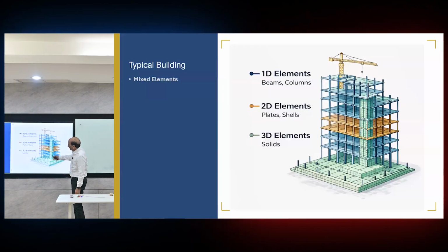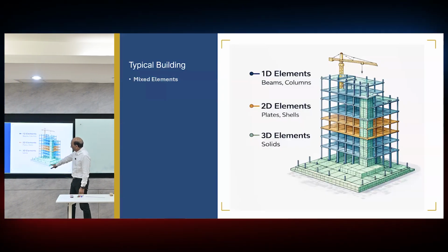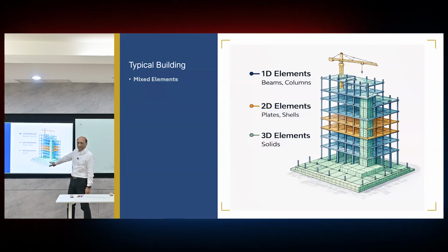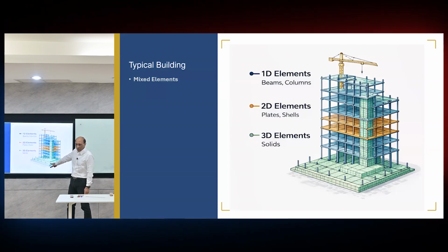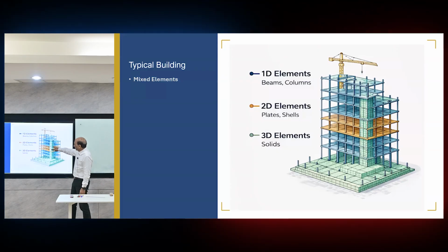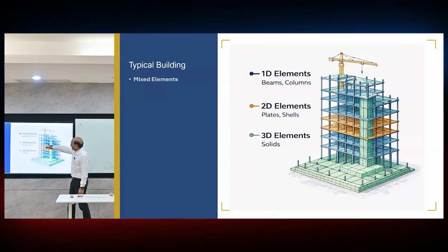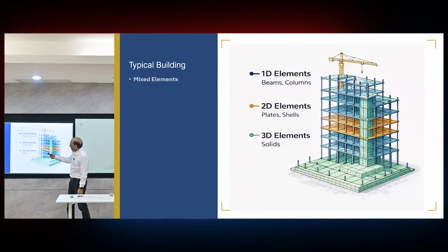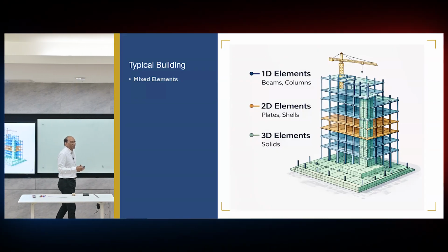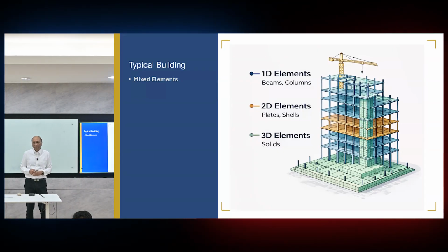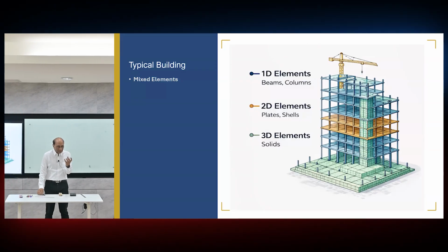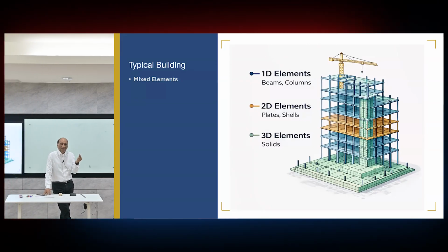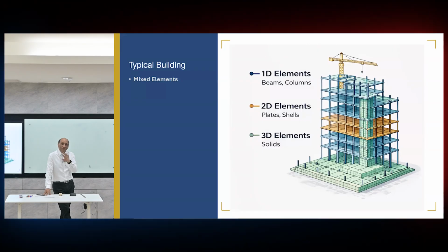So this is a typical building. Solid elements, some people can use. Of course, normally people will not use, but we should use because it's a thick raft there. So it's a solid. Then we use shell elements here, and then we have the frame elements. So you can use a number of different elements in the same structure. So when I say dimension of the element is 1D, 2D, and 3D, not the structure.